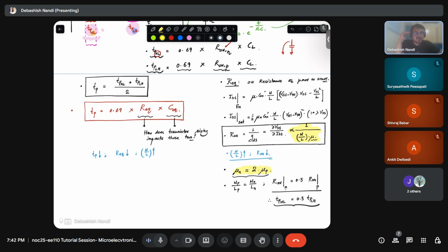So there will be surface roughness scattering that we do not consider in a bulk or pristine semiconductor bar of silicon. So in this case, the values will be much lesser, around 300 to 500 centimeter square per volt second. You see that the surface roughness scattering has reduced the mobility to almost one third of the bulk mobility for silicon.